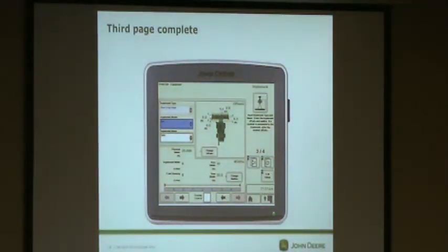How about on a beam platform? Same way. It usually breaks it up into 5-foot sections, or 6, whatever. But it does shut your head down if you've got the overlap control checked. Depending on how you set it up, it might be on your home page, or you can go into the equipment tab in your header. That's a lot closer than saying, okay, I'm taking 30 foot, only taking 5. At least it's shutting it down that much.